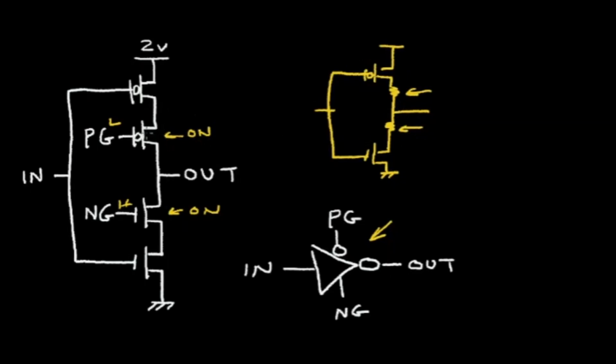However, again, if this PMOS transistor here is off and the NMOS is off, these resistors are open circuit and the output is detached from the circuit. So the output just floats there, or we call it the high Z state. It's completely disconnected from the circuit function.